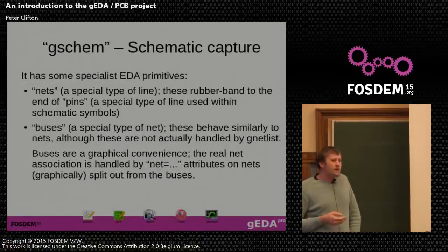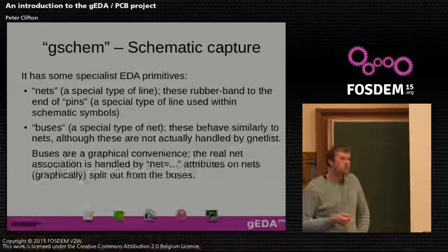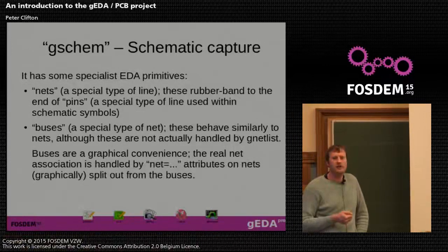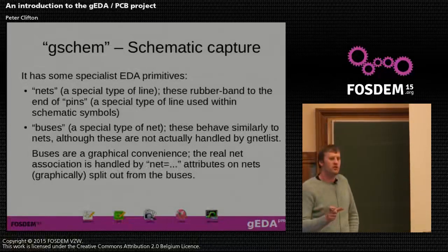Buses, another type of specialist line, although in fact the case of bus is more a graphical line. We don't actually, at the current state of gEDA, process the connectivity of a bus in terms of the signals within it. It's more a construct that you draw on the schematic, and you actually name the individual signals when you pull them out of the bus.